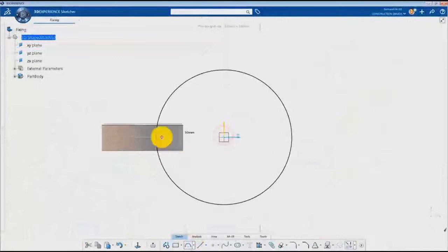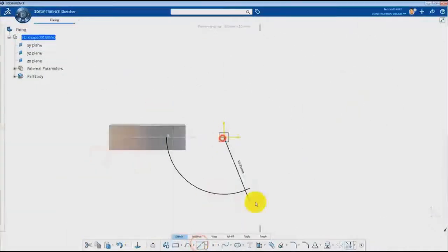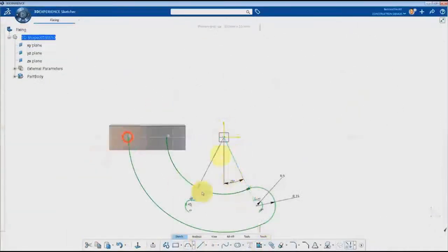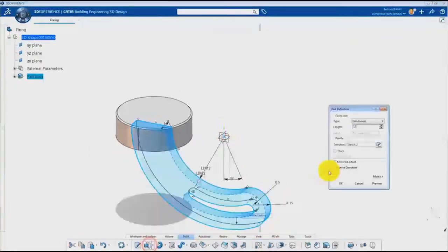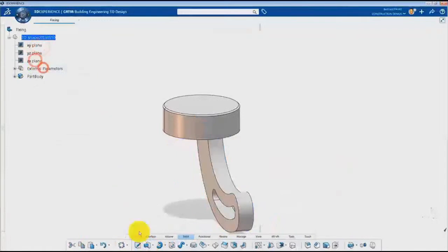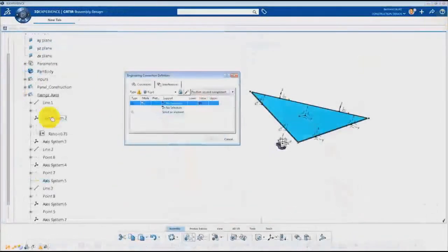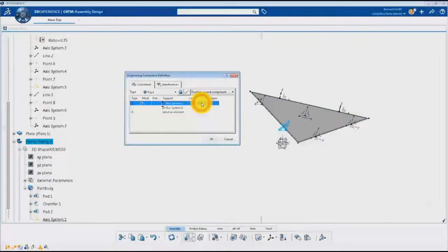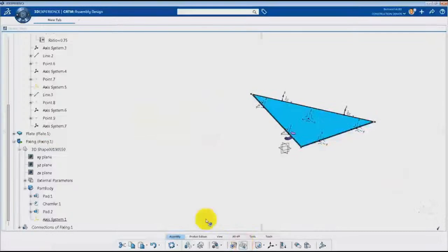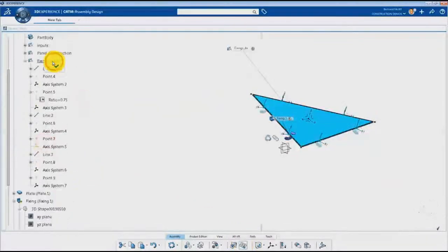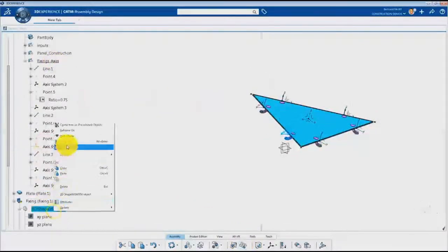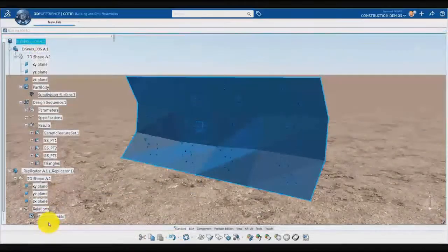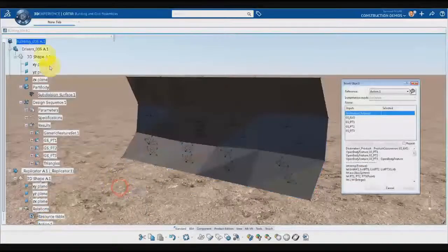And then in CATIA, the rich client, we're going to show you how to model an engineering template from scratch. This is a component, a fixation component that's going to be used to assemble our panels. You see how we create that engineering constraint within our model that positioned our panel. And now we're going to do an assembly pattern within that panel for all of our fixings that are common across all of our panels.